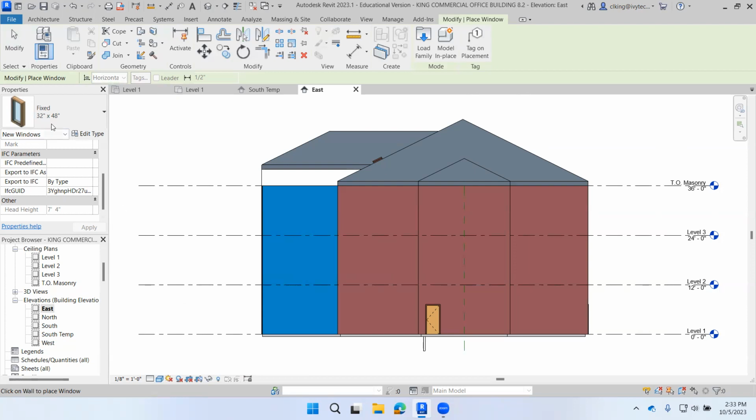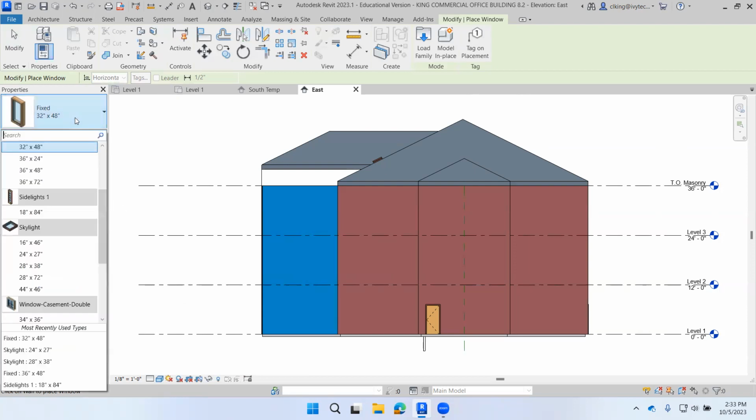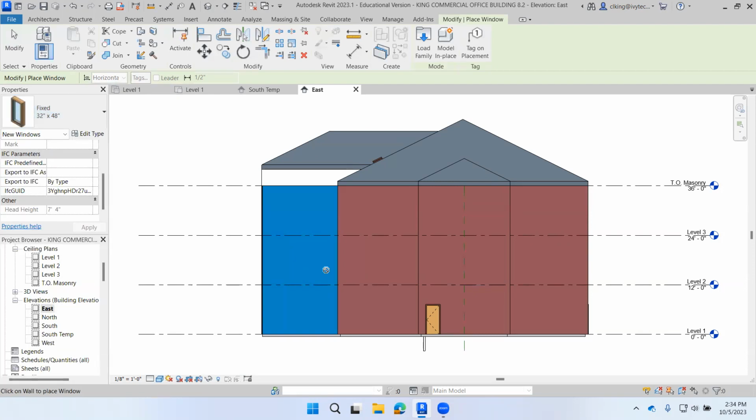You will insert a window in elevation. This will demonstrate first that you can actually add a window in elevation, not just plan view. And second, that the other views are automatically updated.